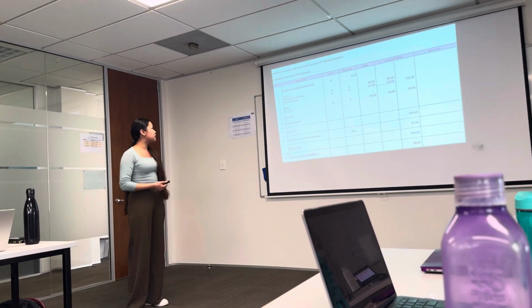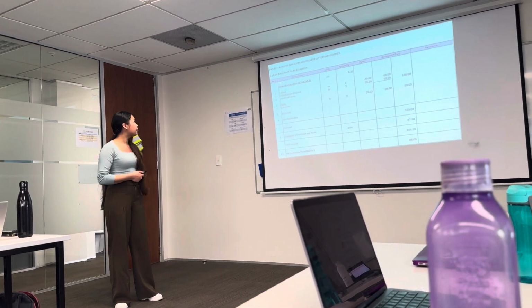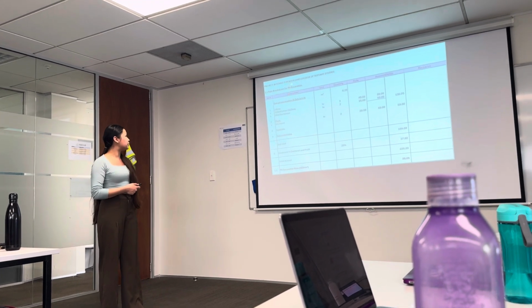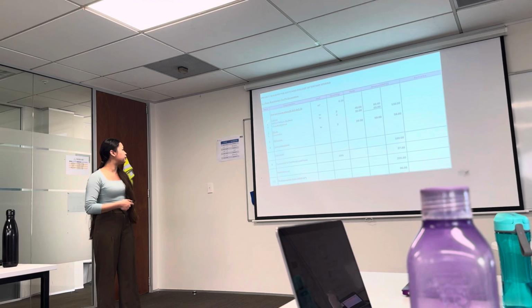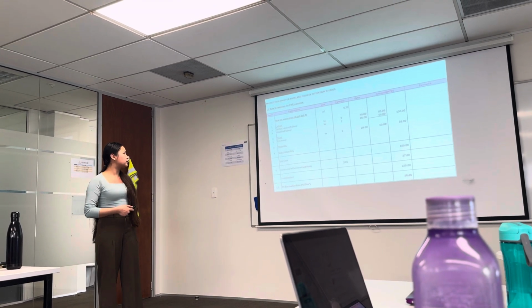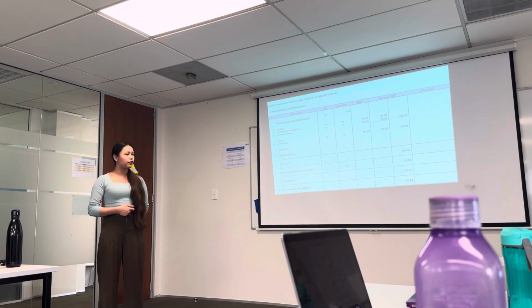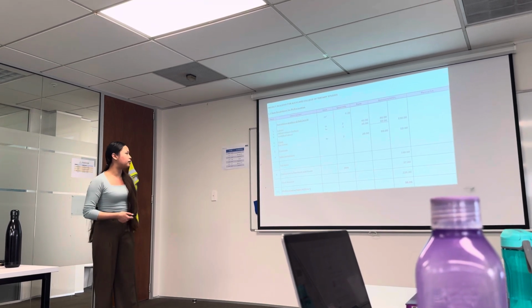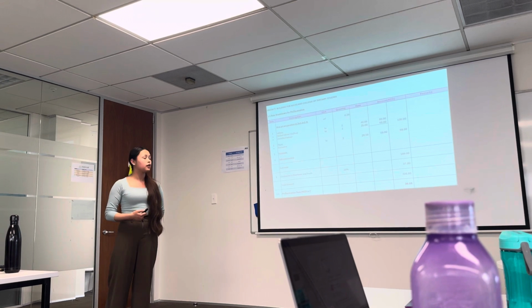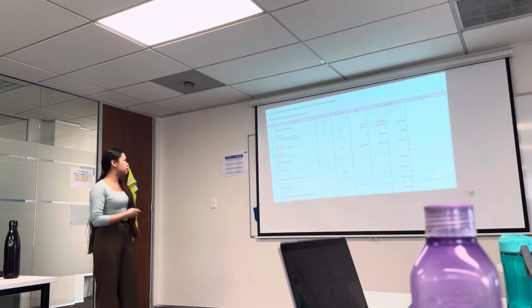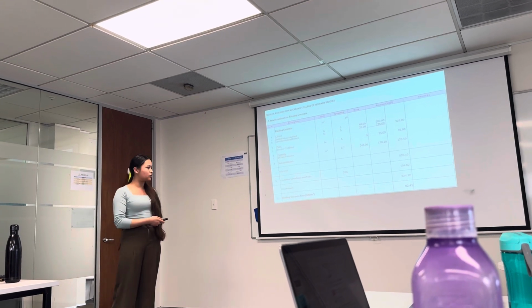So you can clearly see that in the rate breakdown structure, like in the pit excavation, you see the labor, plant, materials, we take it and we calculate it as their per hour rate, and we calculate the amount, like quantity, how many labors we are taking, about the quantities, and so on. So this is for the blinding concrete.